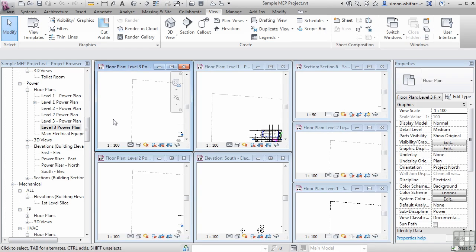While this may be a general practice in other CAD programs like AutoCAD, it's a good idea, or best practice, to keep the number of open views to a minimum. It's not that Revit can't handle this, it's that your computer may not be able to. Because we're dealing with a single database, when you try and edit an object, it will edit that object in every view that is open.